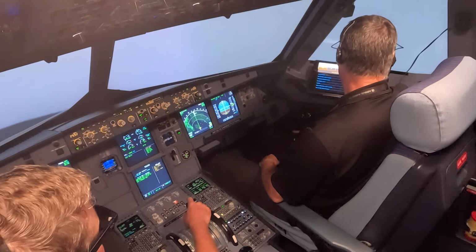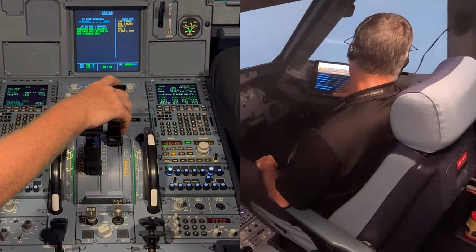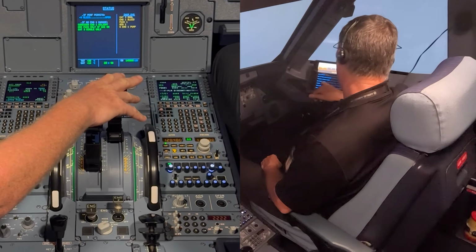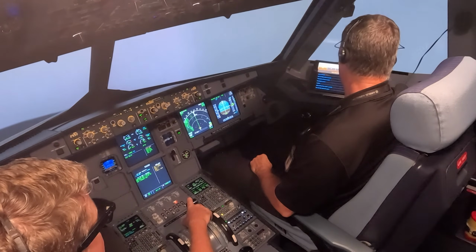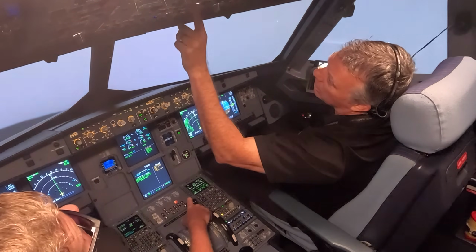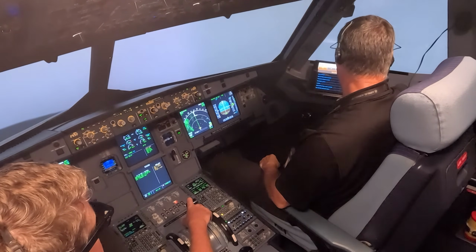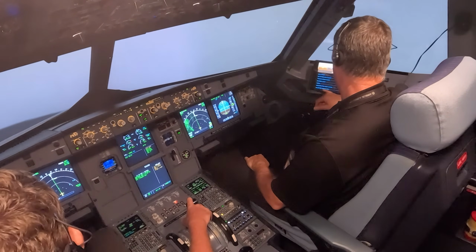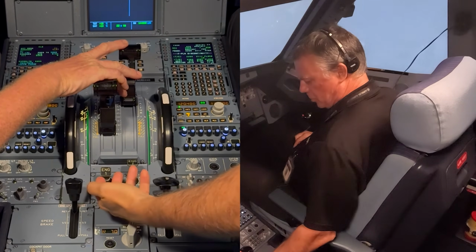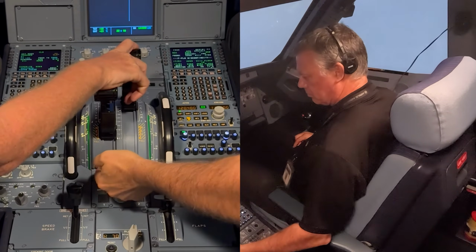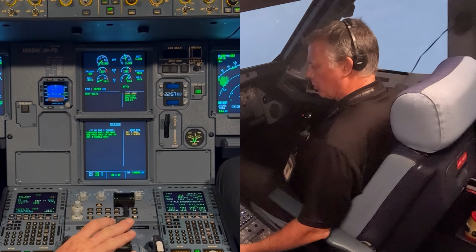Engine master affected, engine off. That's off. Thrust lever affected, engine idle. That's at idle. Engine mode selector to ignition. That's ignition. Cross bleed open. Air cross bleed open. Wing anti ice for starter assisted off. Wing anti ice is not on. Engine master affected, engine on. Confirm engine 1. Confirm engine 1. On. We should get a light off within 30 seconds after fuel flow.